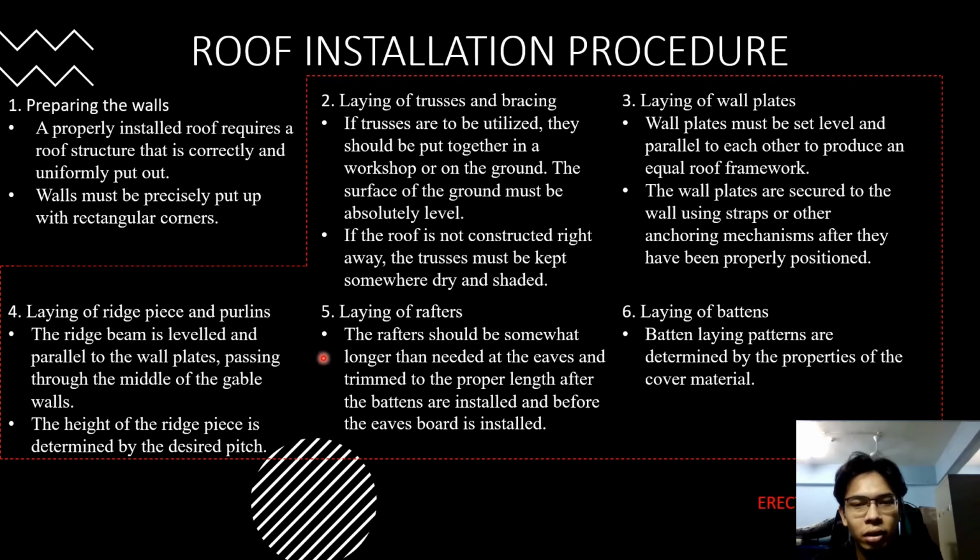Fifth, laying the rafters. The rafters should be somewhat longer than needed at the eaves and trimmed to the proper length after the battens are installed and before the eaves board is installed. Finally, laying the battens. Batten laying patterns are determined by the properties of the cover material.